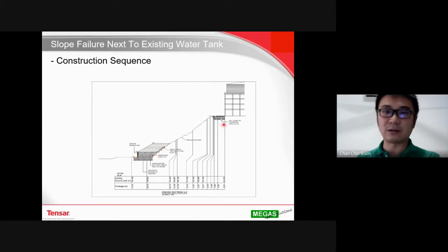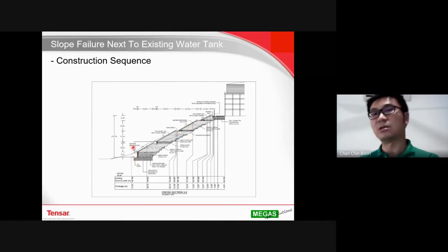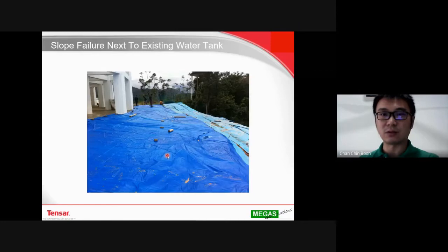We excavate again to remove the loose material at the top, then construct the toe wall for the second slope, follow the same thing, move away again, construct the third slope, and the fourth slope is a small slope where we put in the geogrid and connect it back over here. And of course followed by some drainage system like berm drains, toe drains, cascade drain, and whatsoever. And upon completion, close turfing on the surface of the slope, make sure it's all right.